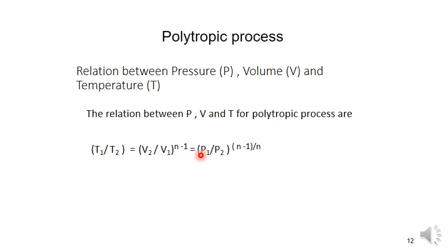Next, coming to the polytropic index. So n is equal to log (P2 by P1) divided by log base e or base 10, we can write anything. If you write the numerator as P1 by P2, we can write the denominator as V2 by V1. Or if you write the numerator as P2 by P1, we can write the denominator as V1 by V2. So log e can be replaced with 2.3 log 10. Both numerator and denominator have 2.3, so both will get cancelled and the remaining is log base 10. So that is the polytropic index n value.